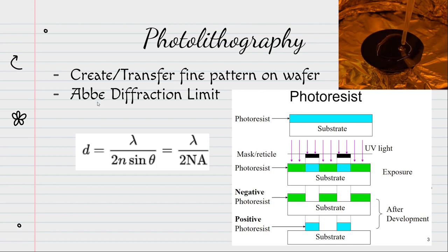Okay. Resolution of lithography is important, and the amount of diffraction will impact the resolution. We want to minimize the diffraction. And from this equation, we can see diffraction is related to the wavelength and numerical aperture. Changing the numerical aperture is not really practical because of physical limits and costs. This is the reason why the semiconductor industry keeps on lowering the wavelength instead.